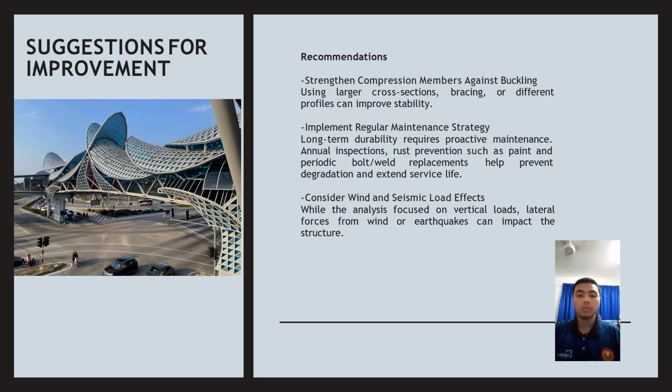Now I want to continue with suggestions for improvement. In recommendation, strengthening compression members against buckling using a larger cross section, bracing or a different profile can improve stability.